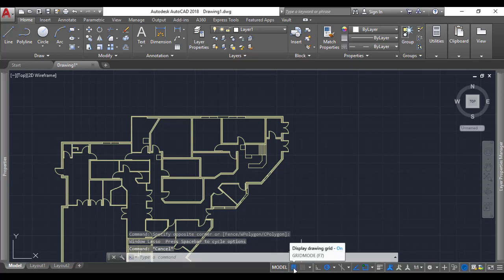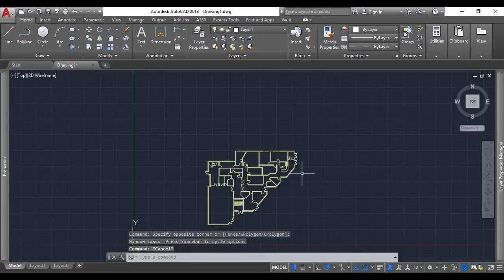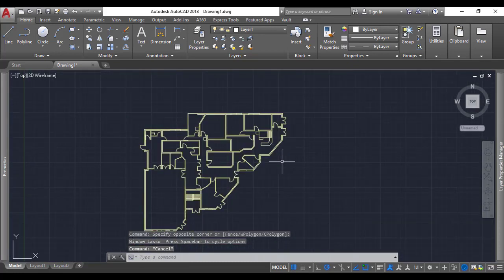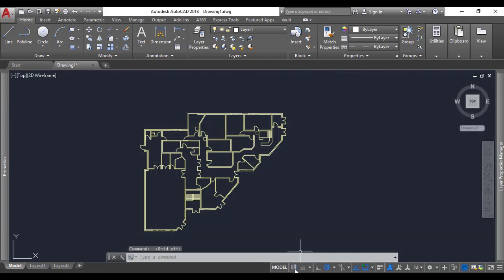We've got our grid display. So if you're busy drawing and maybe you have some faint lines, just drafting lines to see where you're going, some construction lines, and normally their transparency is set a bit higher, so you can't really see them so nicely with the grid at the back, then you can go and maybe just put your grid off.